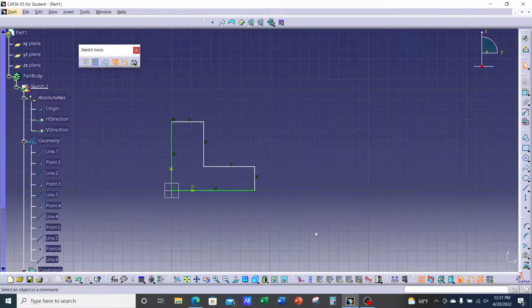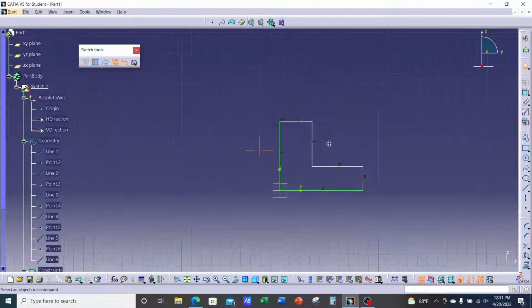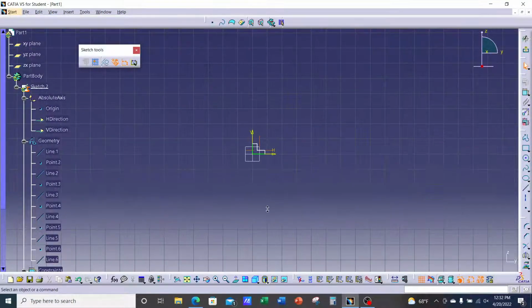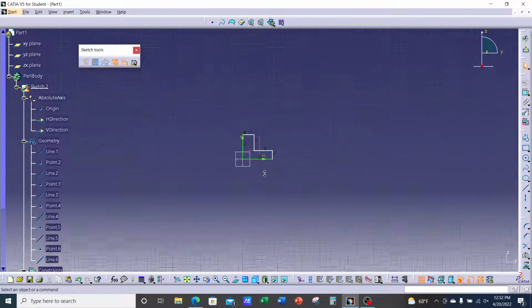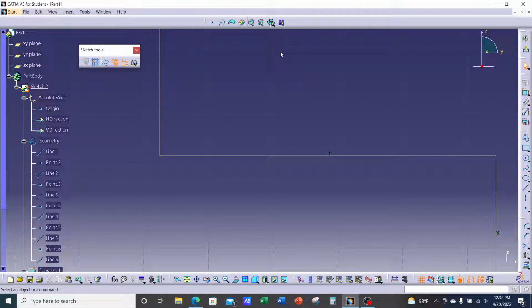So let's practice. Okay, so to pan, hold the wheel, move the mouse. That allows us to pan. Now I'm holding onto the wheel and I'm going to tap the right button. I'm just going to tap it and I'm only going to hold on to the wheel. So I tap the right button. Now I move the mouse up and down. And I can zoom.